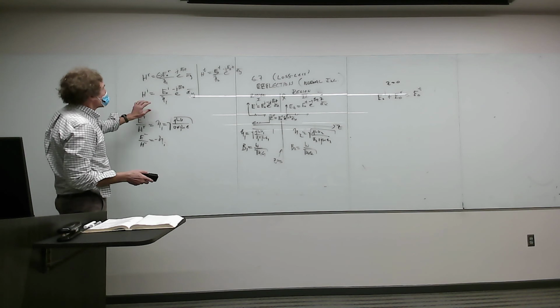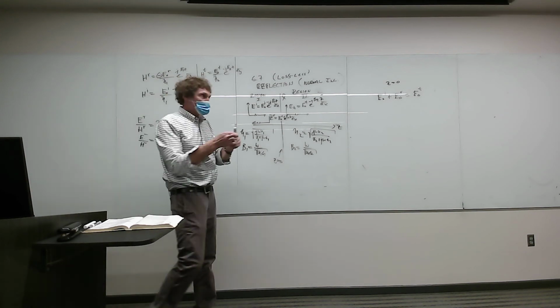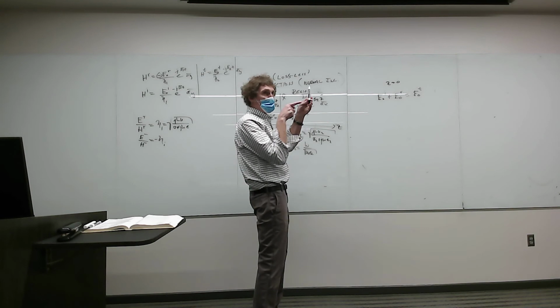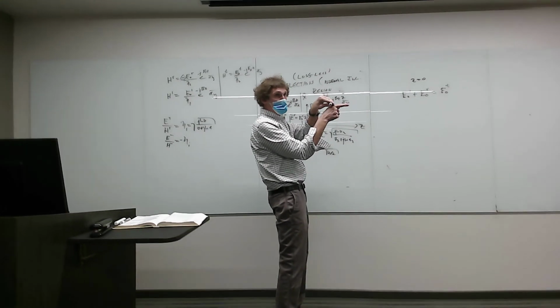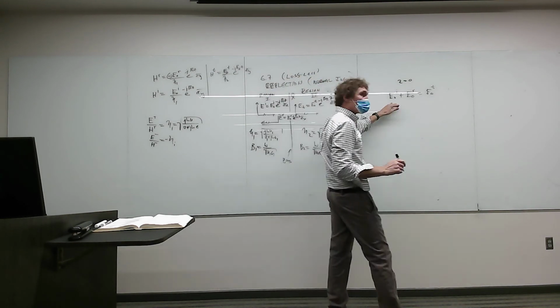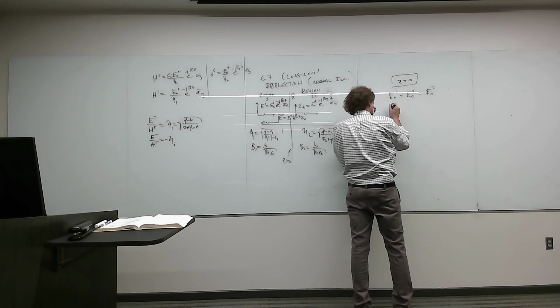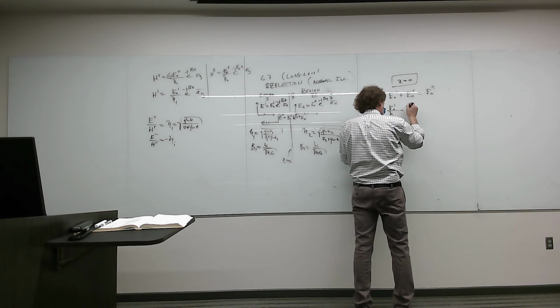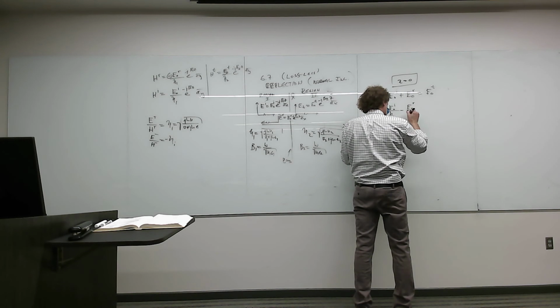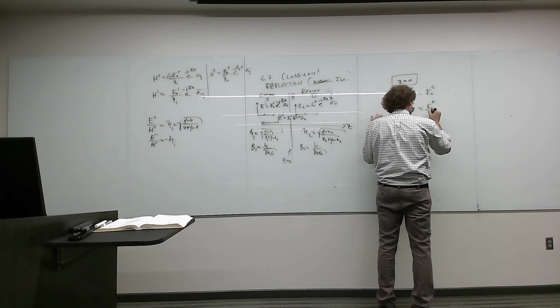All right, so these are the three H field equations. And if you have an E field that's vertical, and it's propagating that way, the H field has to be perpendicular to both vectors, and it's also tangent, right? So H tan 1 is H tan 2, and over here, we're doing this at z equals 0. What that means is E naught incident over eta 1 minus E naught reflected over eta 1 is equal to E naught transmitted over eta 2.